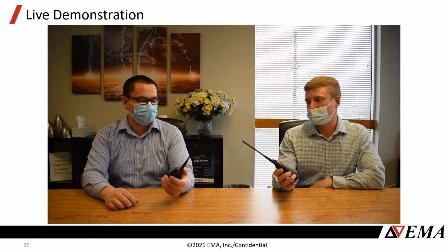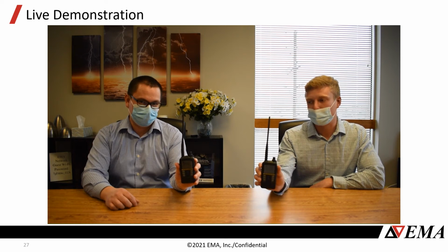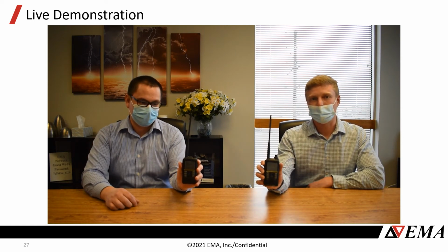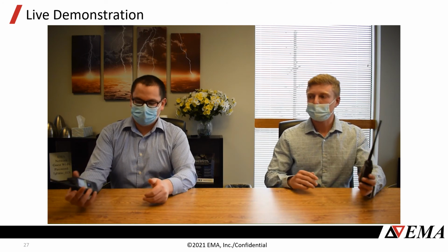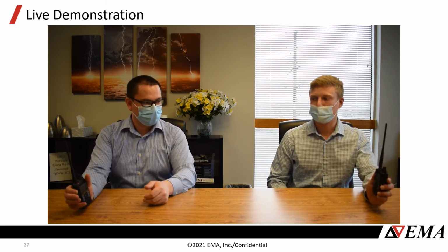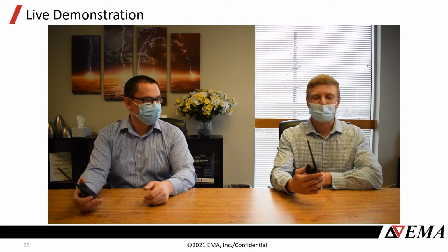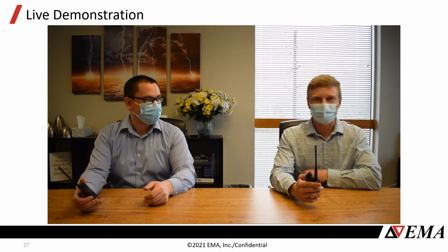So we've got Juan's radio tuned right to 430 megahertz, and we're going to demonstrate that you still get interference between these systems. Ready? Yeah. So as you can see, there's a very audible interference there, and that's due to that mixer product.